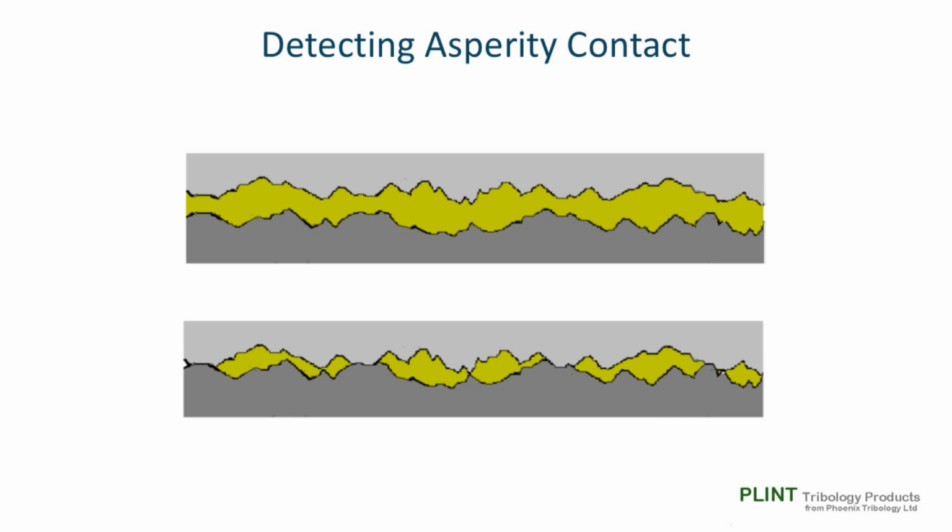Oils are good insulators. If the surfaces are brought together but remain out of contact at an asperity level, the switch will still be open circuit, so the contact resistance signal will still be high. In effect, once there is no metal-metal contact in the switch, it does not make any difference whether the surfaces are separated by 100 microns, 100 millimeters, or 100 meters.